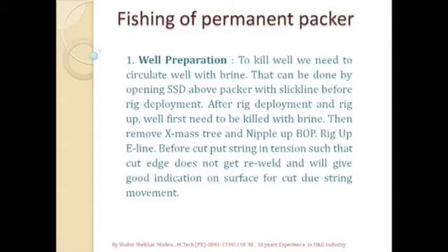Here we keep the string in tension so that after the cut the edge should not get re-welded, and in that case we would have to attempt the cut again. Also, keeping the tubing in stretch condition gives a good indication on the surface of the cut, because if the string is in stretch, after the cut the string will move and it will give the indication of the cut.